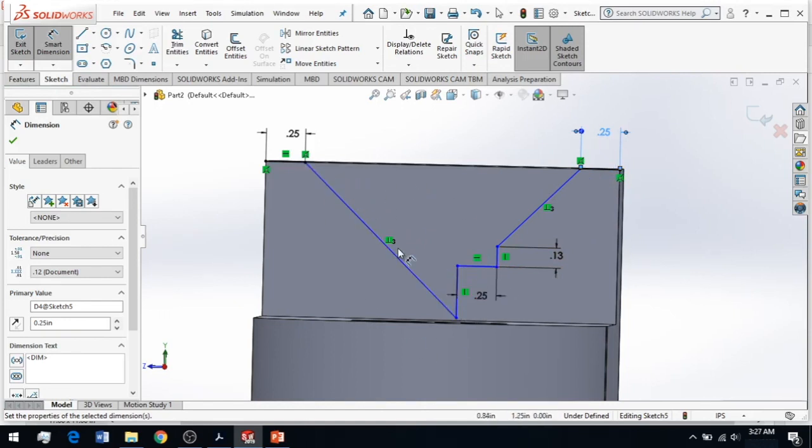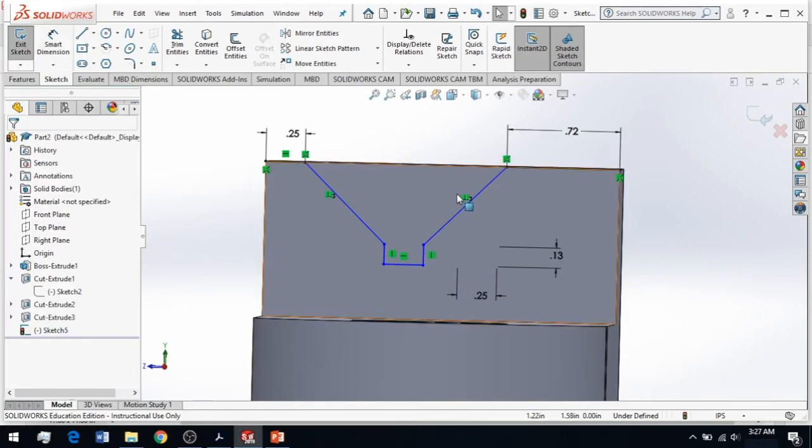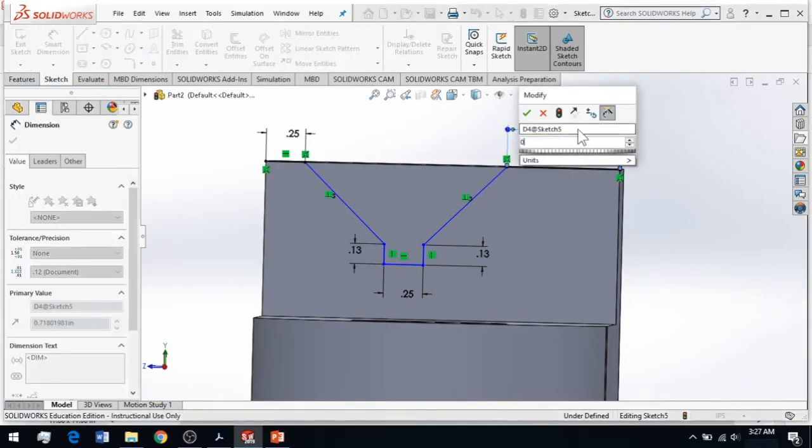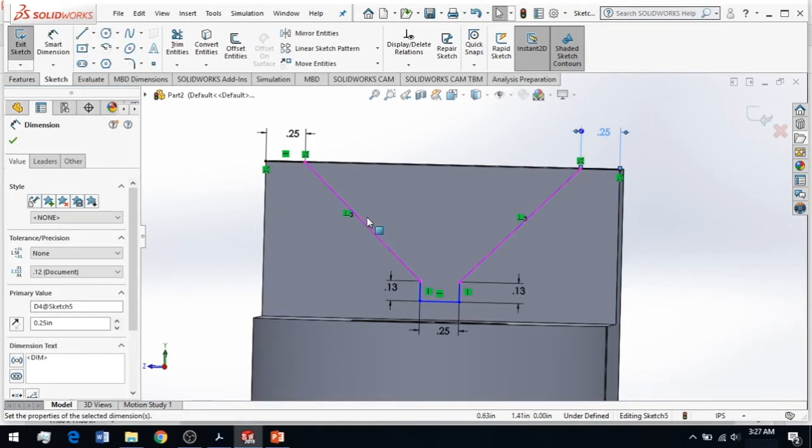the shape of my profile because I didn't define this line here. So the software automatically changed because I didn't put the restraint on the other edge. It changed the dimension of my line. So I put the Control Z, and before I do that, I just put the dimension here, make sure that I define this line. So when I come here, double click on this and change it to 0.25, you can see that my original shape here stayed the same. So I define each line.